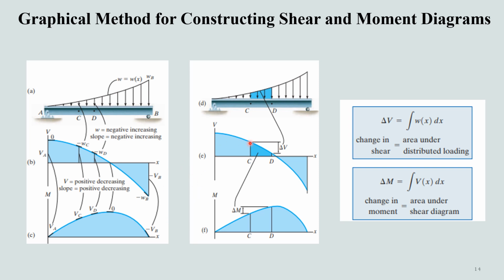The equations developed in the previous slide can also be written in integral form. If we take an integral of the differential equation, we find that the change in shear is equal to the area under the distributed loading.